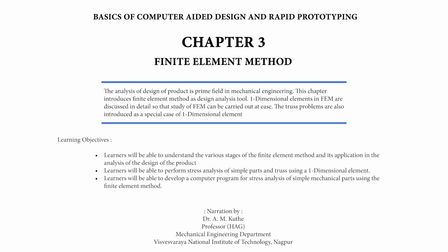Para 3.4 Shape function. To get strain and stress over the element domain, the function is selected where the displacement of the nodes is the input. The polynomial expression is selected to get such value. Consider an element E as shown in figure 3.8. The element is shown with the two nodes having displacement u1 and u2. P is any point on the element which is shown at x distance from the node having displacement u1, and L is the length of the element.